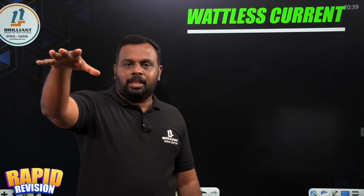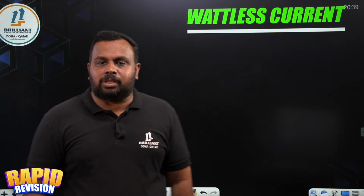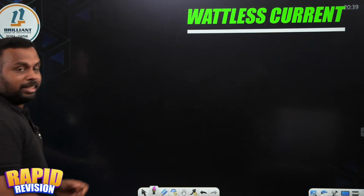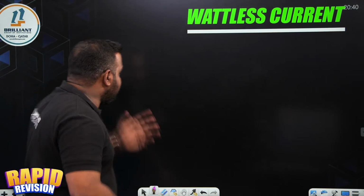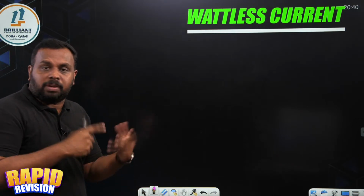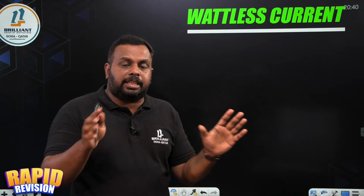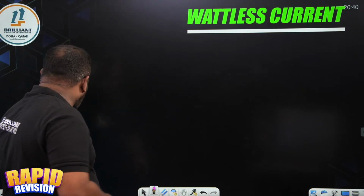Wattless current. Name itself you can understand. What is wattless current? Watt is the unit of power, you know that. Wattless, no power. So a current which does not do any work in a circuit, it is called what? Wattless current. So what is the example for that? Current through an inductor, because in an inductor power factor is 0, so power will be 0. Capacitor also, the power will be 0, which means wattless current. Examples for wattless current, if they are asking: current through an inductor and current through a capacitor. Okay, so that's all about wattless current.